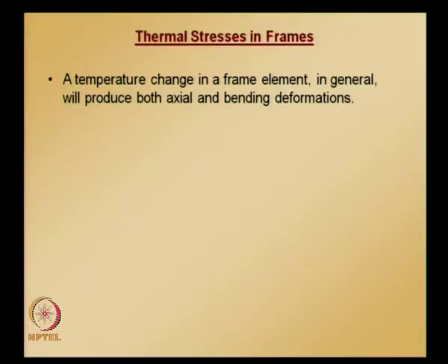So here in frames, in addition to this bending moment, again no shear forces will be there. And if it is a plane frame, because of these temperature changes we are going to even have axial force effects. That is what we are going to see in today's class. So temperature change in a frame element in general will produce both axial and bending deformations.